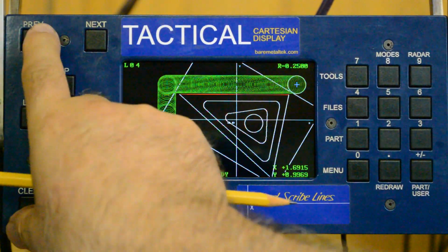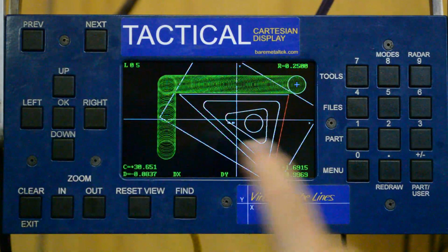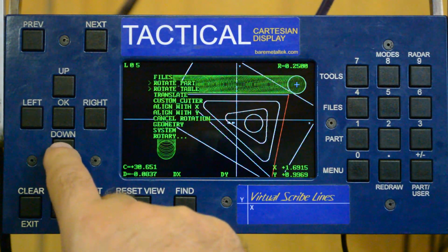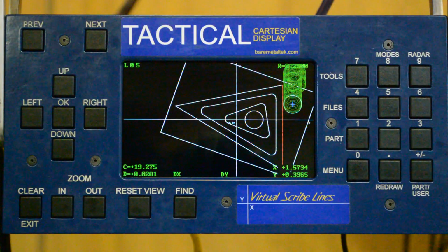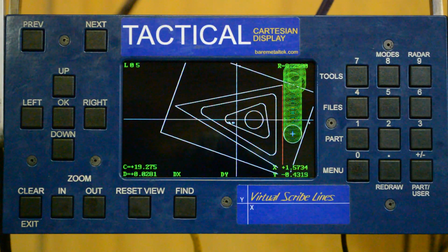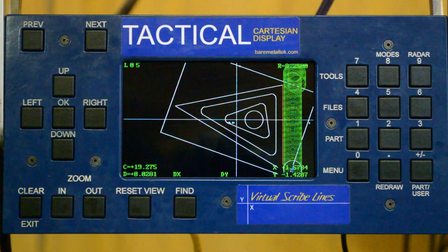And then I'm going to set this line here parallel to the y-axis. Again, bring my Z down to depth and make however many passes I need at different Z depths to get to the bottom. Okay, that's going to be the roughing strategy.